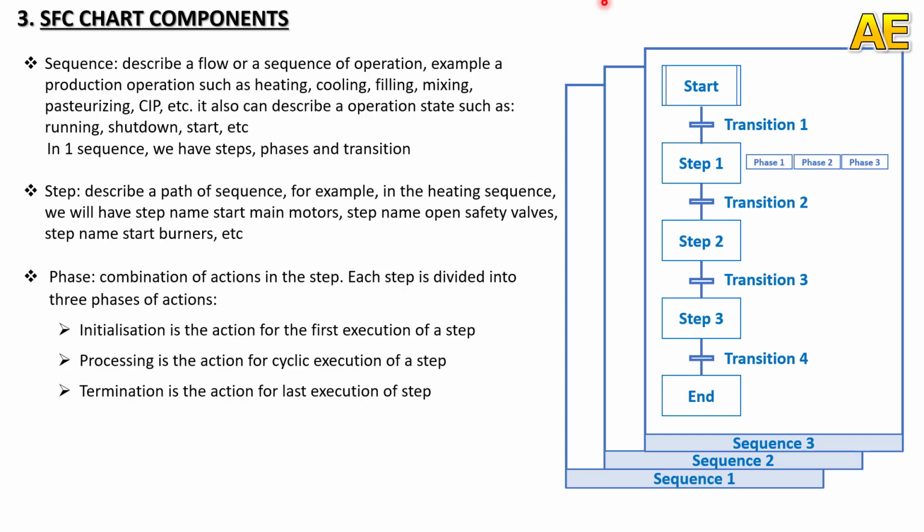A transition has the states true and false, and the state of the successor transition of the active step is queried. If the successor transition is true, it means the condition is true. The previous step is inactive and the next step is activated.